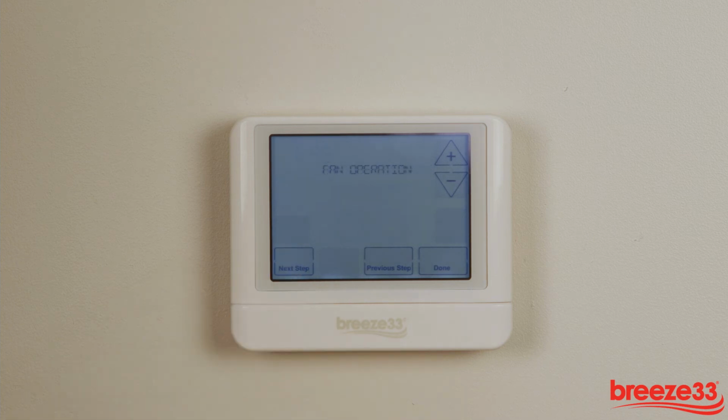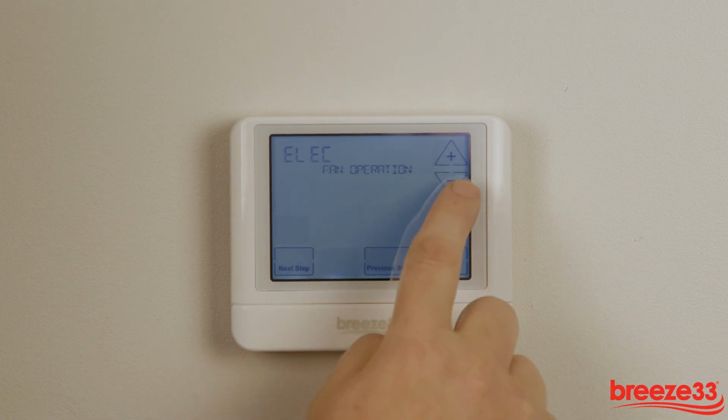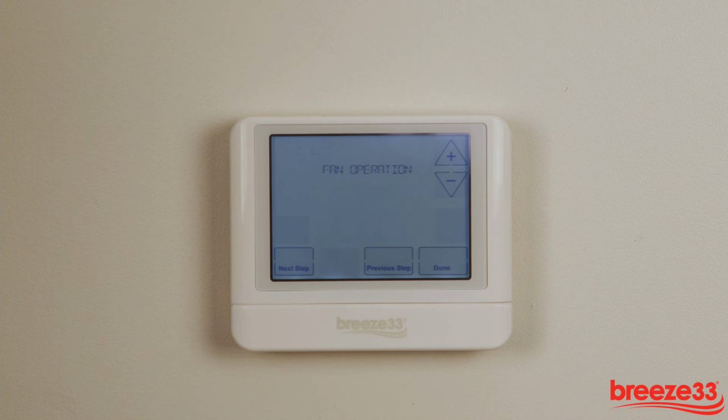Fan operation. Select GAS for systems that control the fan during a call for heat. Select ELEC to have the thermostat control the fan during a call for heat. Morning recovery. This feature will start heating early to bring the building temperature to its programmed set point by the beginning of the wake time period. Use the negative or positive keys to turn this feature on or off.